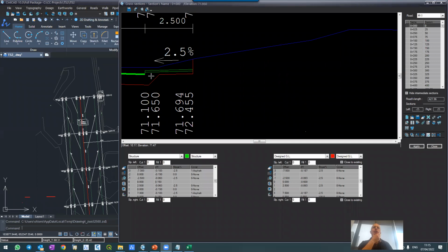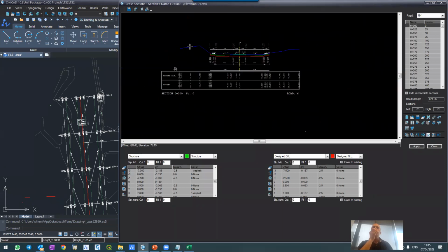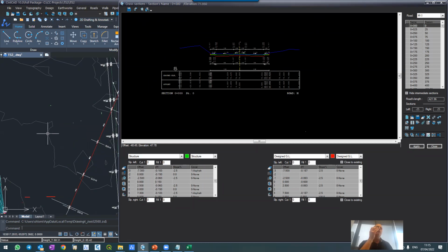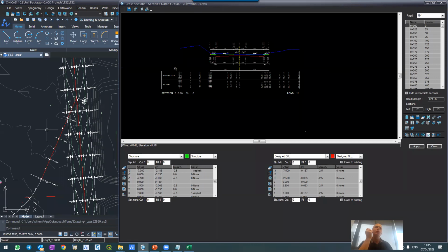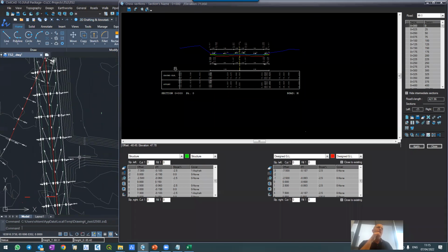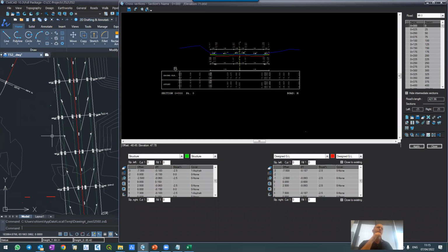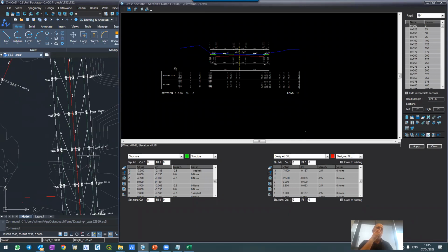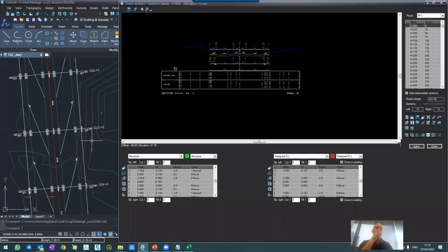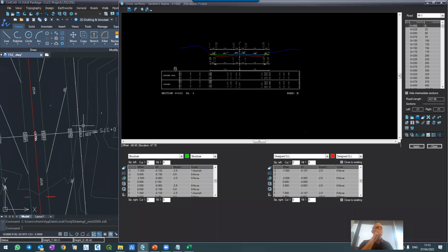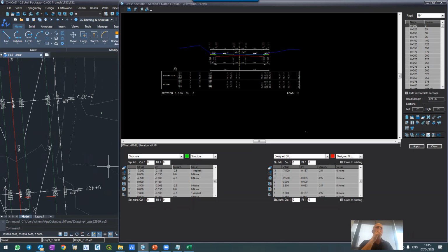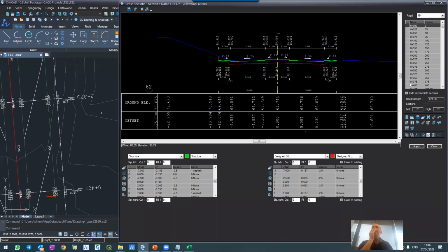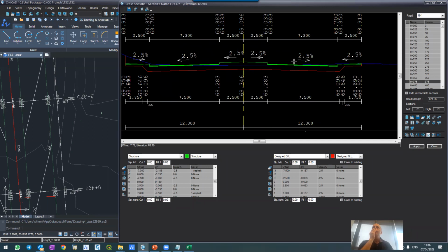Okay. Someone asked me what happens if the road changes the width. There are many ways how to do it. There's a method named extract, but I can even change a specific segment. You know what? Let's do a sample here. Take this 375 and 80. I'm going to 375. And what I'll do, I'll take this and instead of 7.3, I'll make it 8.3.